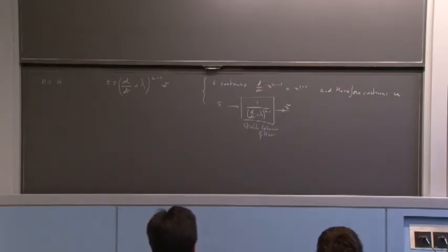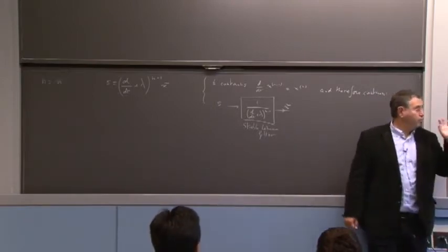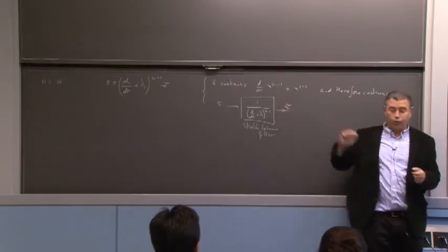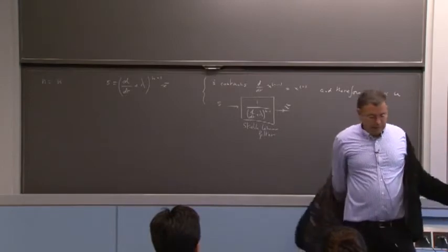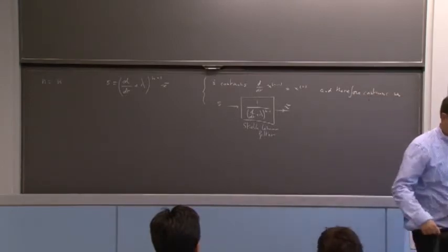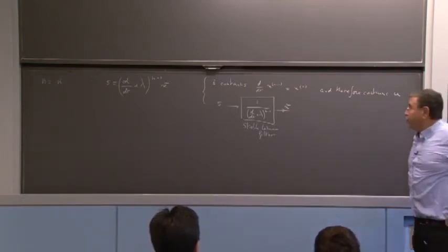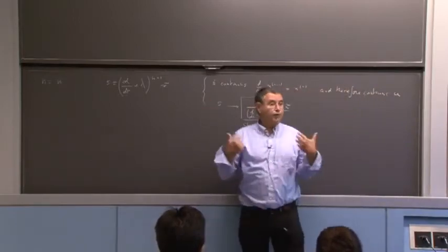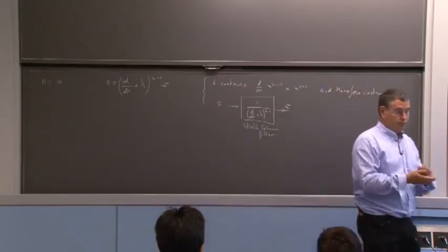So this shows that by picking this intermediate variable S, you can replace the original nth order problem by a first order problem, and guarantee that if you manage to solve the first order problem, then you'll have solved the original nth order tracking problem. Okay?